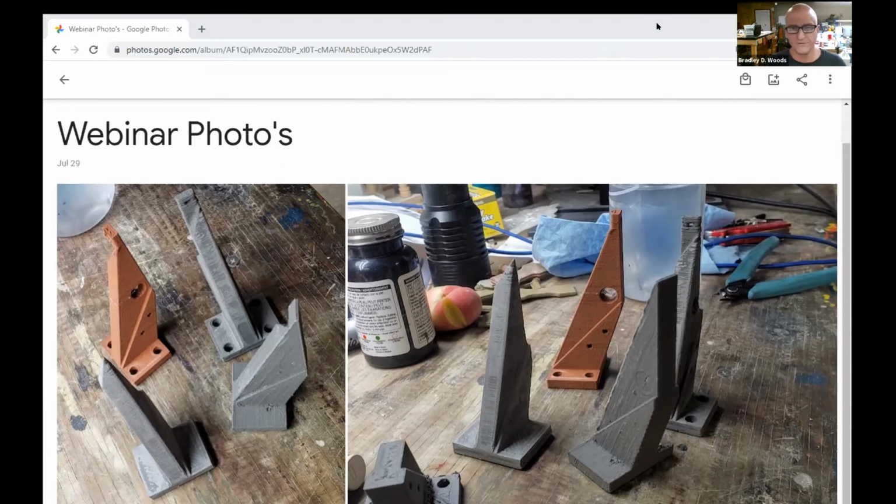One of the things that I've noticed is all of the major slicers right now, Cura specifically, are designed to save time in the printing process. They're not necessarily designed to have high quality infill. So they'll lay down the infill lines only every other layer, so you get a very poor print.